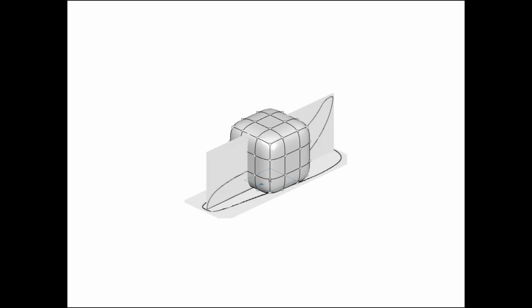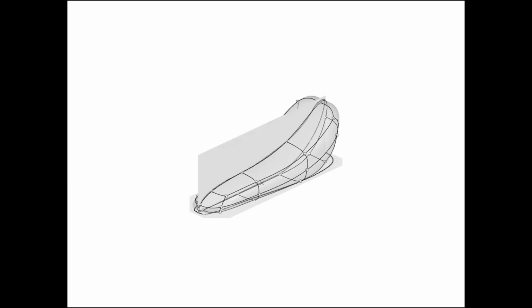One extremely useful xShape modeling technique is to insert sketches or pictures into the physical product and use them to shape the outer edges of a primitive subdivision surface. These pictures can be inserted into planes, scaled, oriented, and placed within or behind the model.